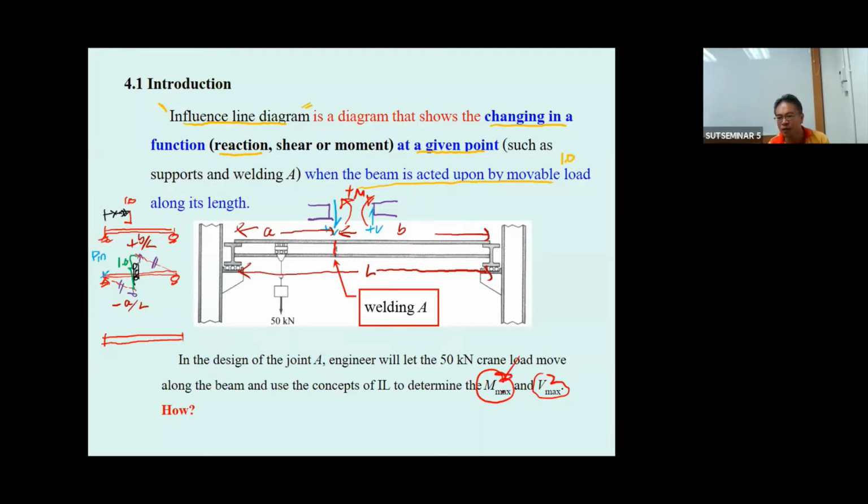And then if you prefer to find the Mmax, what you're going to do is you're going to draw the influence line of the moment at point A. So the support here and here is going to be the same. You need to change this one into the hinge to release the M sub A, positive M here. Okay, and then you apply the moment to this point. When you apply the moment to this point it gonna move up to here. And since this one is the rotating point, you get the shape. This is going to be the influence line of M sub A.